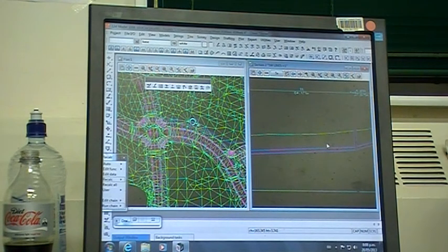But on the other hand, the bigger the pipe, the more it costs. For me as a developer, my boss is the client, so I've got flexibility financially. If you work for a consultancy, every penny counts, they've got a budget. Any time you spend money you don't have to, it comes off their bottom line, and they get funny about things like that. So what you need to do is keep the pipe as small as you can without compromising yourself, and also as shallow as you can to keep the cost down.